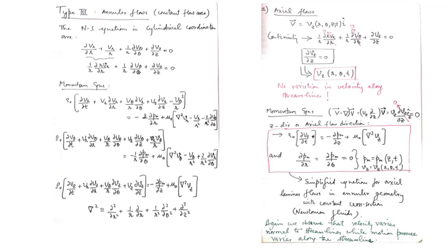Now coming to axial flow first. So A, axial flow. So velocity for this axial flow is Vz, and it should be Ez cap. In fact, it is incorrectly written as I cap because in cylindrical coordinates the unit vectors are er cap, e theta cap and ez cap. So please make a note of this and make a correction. Vz, which is a function of in general r, theta, z and t, all coordinates and time, and of course the corresponding unit vector ez cap and not I cap. Okay.